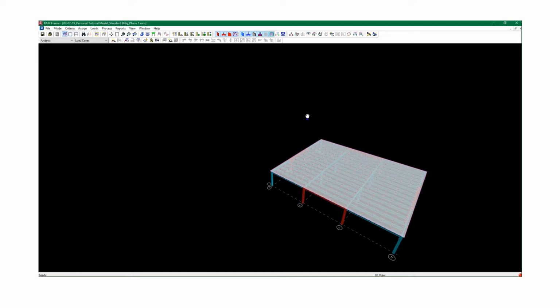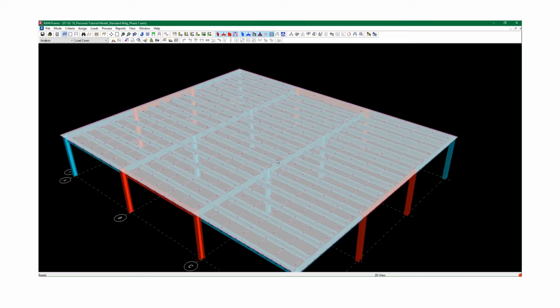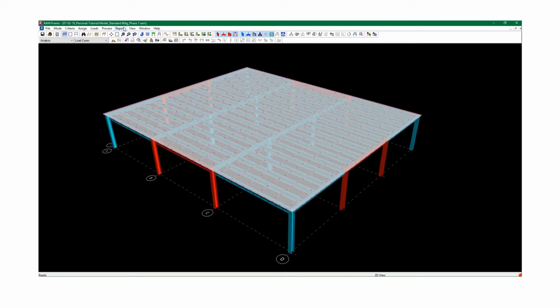Let's reset the structure real quick. All right, so I save my settings. The next thing is, of course, you have your modes, and you're in analysis mode or a design mode. The design mode would be the steel mode right here. In the analysis mode, you could be looking at load cases or load combinations. In the steel modes, you could be looking at your standard provisions or your seismic provisions, depending on the type of structure it is, your R factors, etc.